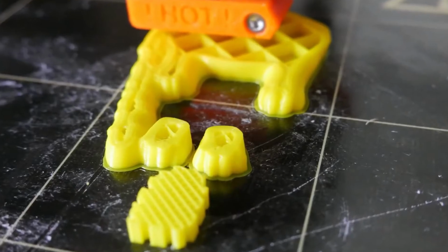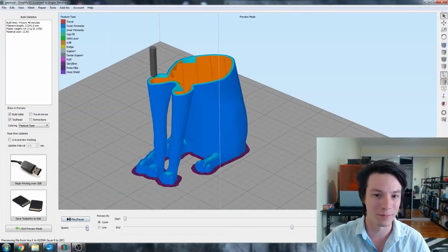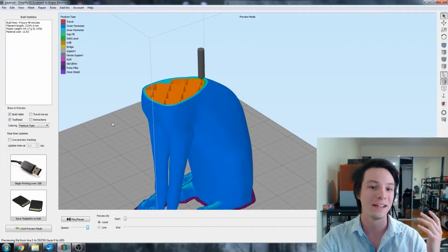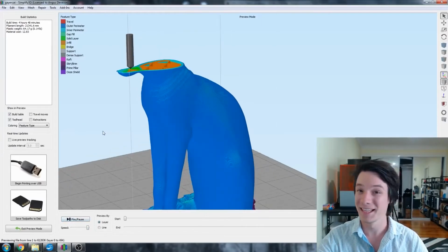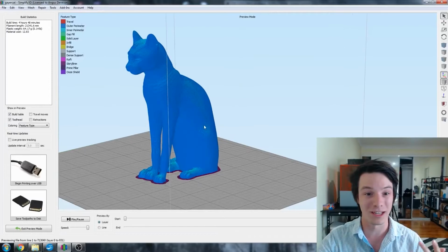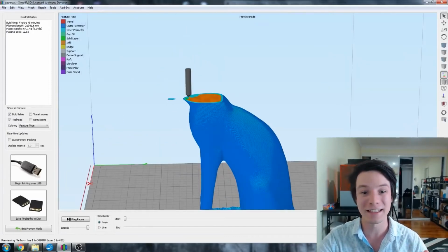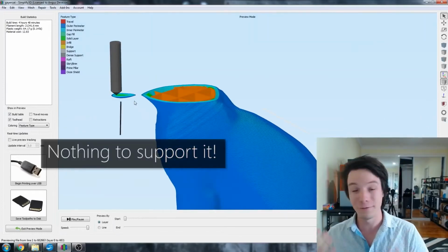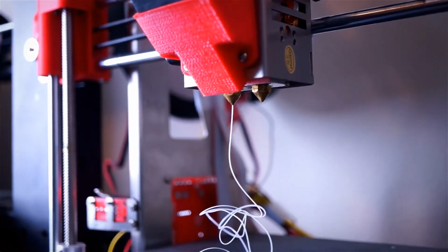Now, because we're dealing with additive construction instead of subtractive construction, like we talked about in the last video, there's another thing we need to consider with our 3D printed models, and that is support. The typical FDM printer that we'll be using for a lot of our modeling purposes is going to be extruding PLA filament vertically downwards. And so that means if we get to any point in our model where there is no model beneath where we're extruding out, we're effectively extruding filament out into air. And so you can guess what's going to happen next: lots of noodles.